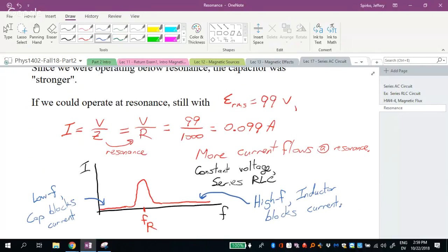If you push them at exactly the same frequency that they're swinging, then you can give them a boost, they can come back around, and you give them another boost, they can come back around, you can give them another boost. That is a similar relationship between a stimulus and a result that happens here. So this F here is the stimulating frequency. That's the frequency we have our power supply set to. And depending on whether we set our power supply, our signal generator, to the resonant frequency or a different frequency, the current is the result, the response of the circuit.